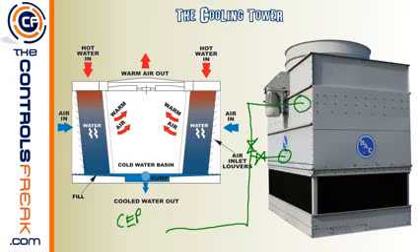And these 2 valves will be linked together with one actuator. And what they'll do is they'll bypass the water. Instead of going across the top and coming down and getting cooled, they'll force that hot water directly into the basin, and in the back over here where the pipe is cooler and the cool water is getting sucked to go back into the CEP, going this direction. Therefore, they're putting the hot water directly into the basin without going down across the tower here and getting cool. They'll just bring that right into the basin of water and get sucked back in.